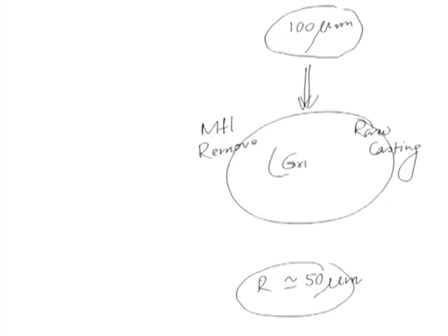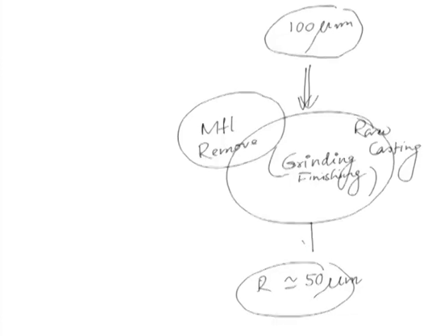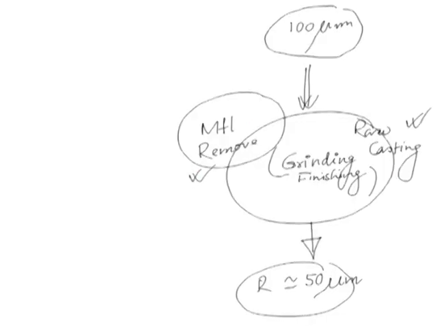This process may be, say, grinding or some other finishing process. Now, from where will this additional material be sacrificed? This indicates that we may have to allow some additional material in the raw casting itself. That means the pattern has to be made a little oversized, so that it produces a little bigger casting than required, and this additional material will be removed as part of the finishing process as we have discussed here, which will ultimately give us the required dimension.